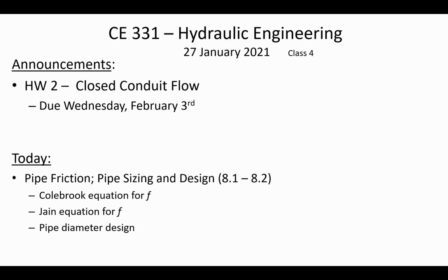It may depend on the circumstances. Like if it says to find the pressure change in a pipe, then you'd presume that the pressure is decreasing, and so that would be the lower pressure minus the higher pressure. So it would be P2 minus P1 that would tell you the pressure decrease. But if the problem statement already says how much the pressure decreases, then you don't have to put the negative sign into your answer.